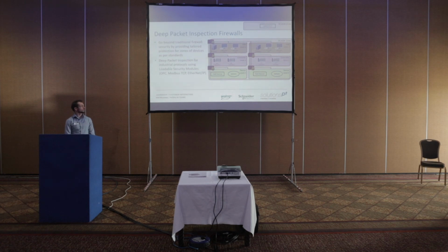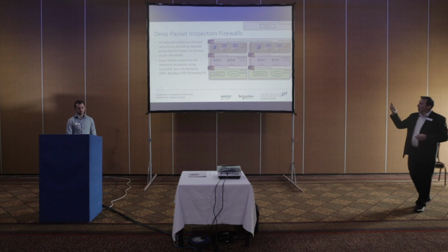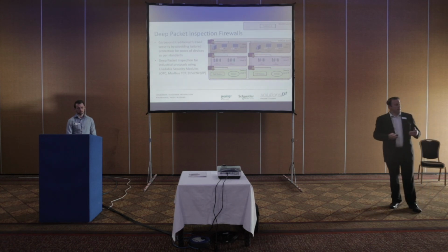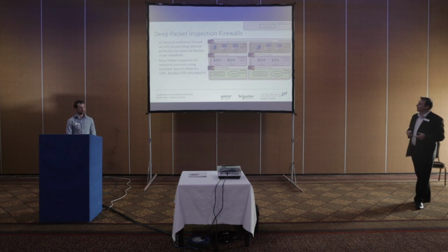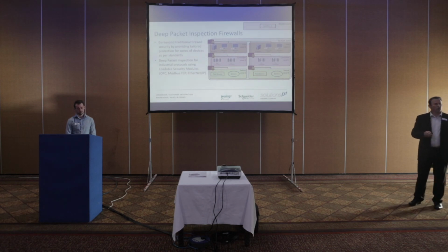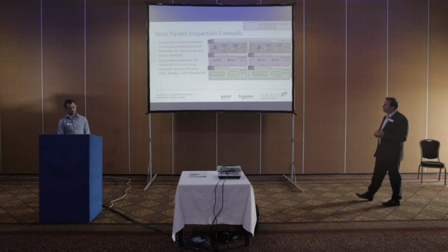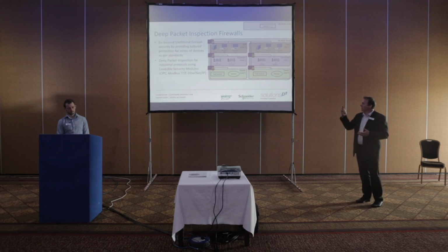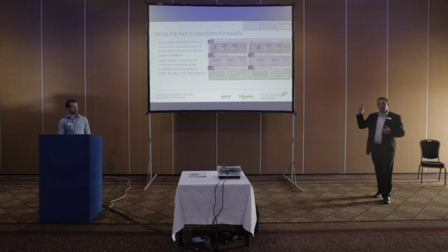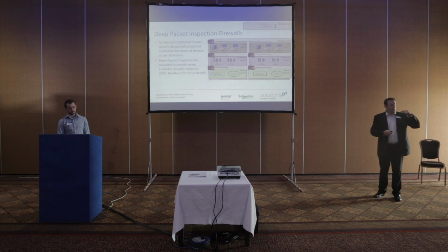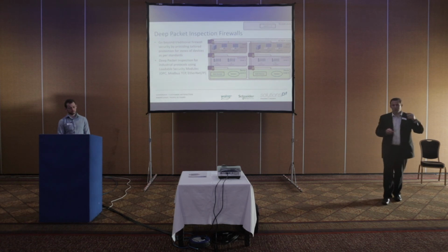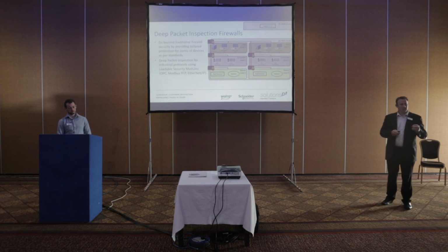You could take this a little bit further and use firewalls that do deep packet inspection. What we mean by that is firewalls that actually understand the OT protocols, such as DNP and the Ethernet-based Modbus. This allows us to secure our zoning between the SCADA and PLC layer, in that the firewalls are only going to let through the information that they understand.